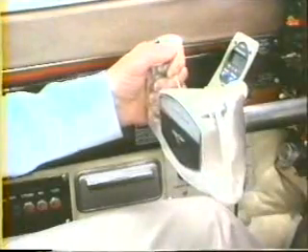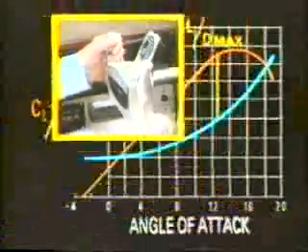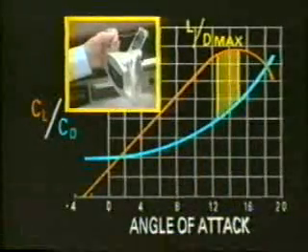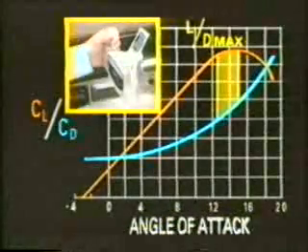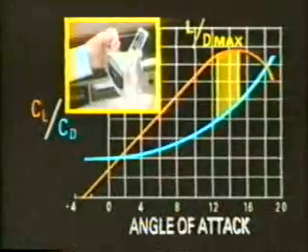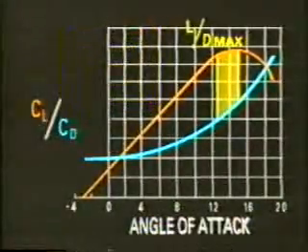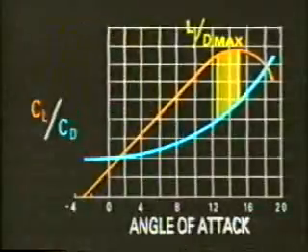We can demonstrate this by looking at two airplanes of different weights during a power-off glide. Since the glide ratio is based only on the relationship of the aerodynamic forces, the airplane with the greater weight needs greater lift. If you attempt to generate the additional lift by increasing pitch, the angle of attack increases above that for LD max, and you will not achieve the optimum glide ratio. Therefore, the added lift can only come from an increase in velocity.